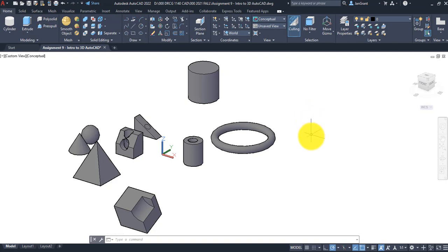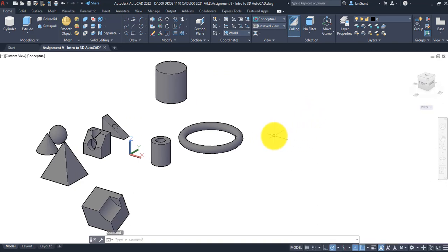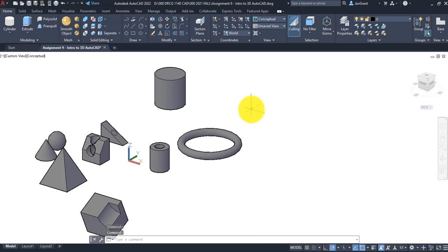Also, we're going to insert one of the drawings that we did previously. It doesn't really matter to me which one it is. We're going to insert it and then use Press Pull to turn it into a 3D object. Then I'm going to introduce to you in this video how to use the layouts at the bottom left corner, and we'll move forward using those layouts for our 3D projects until we look at another way of doing that.